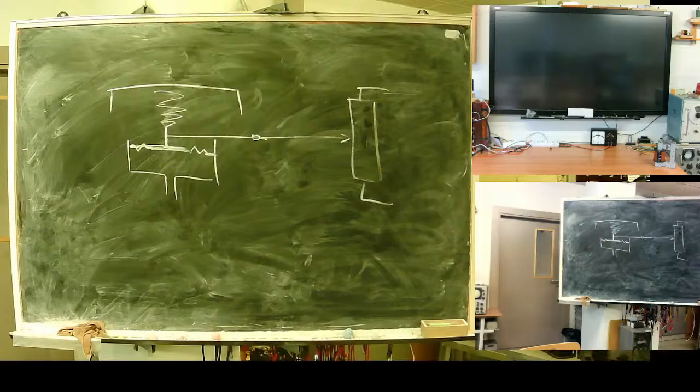Also, mechanical opening of guide valves. When you need feedback from the system, when the system operates, you need the mechanical position of guide vanes. Getting it with a resistor-kind sensor is nearly impossible. They do not survive. Water and vibration, vibration and water.